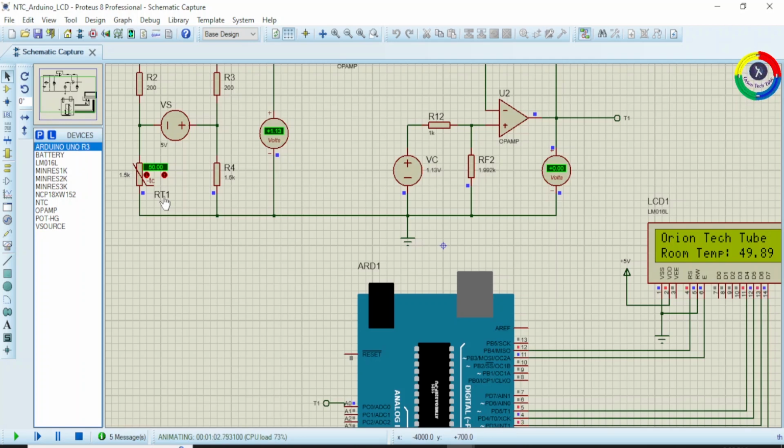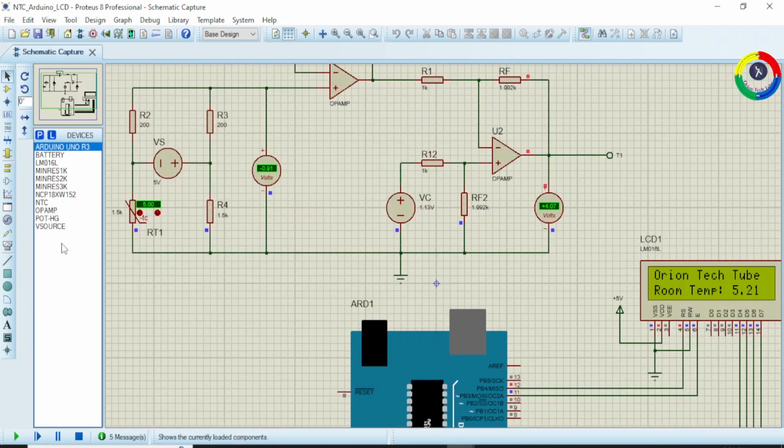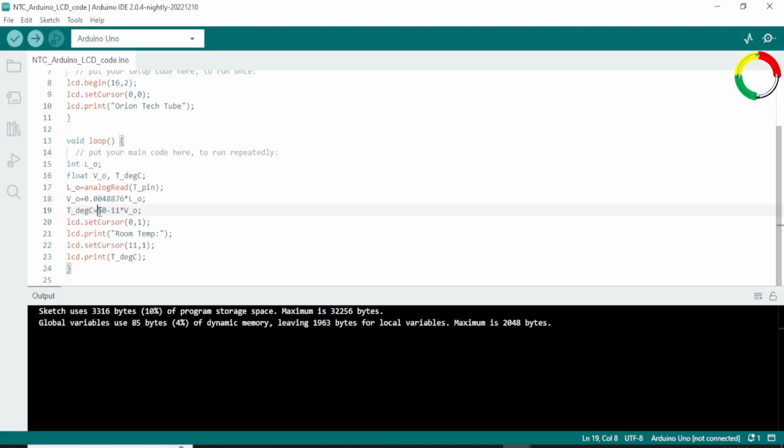Let's make our display fully informative by adding a unit. For example, this temperature is in degree centigrade, so we need to display degree centigrade next to this value. So we need a special character for degree, and let's create it and make our program more clear. Let's round this temperature value to the nearest integer by writing here round, and let's shorten this text to rtemp to save some cells of our LCD and start the value at 8.1.